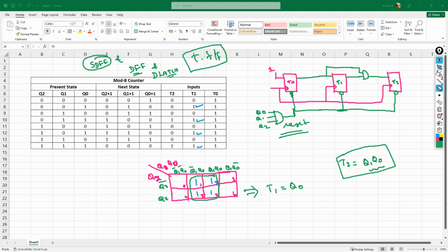Normal design. No, it is not a macro. Macros, we usually call them the memories or other bigger circuits. A counter is very small. You see hardly 3 or 4 flops and 2 or 3 gates. If you really wanted to do this as a macro, you can, but I don't prefer converting a counter into a macro. It would become very inefficient.